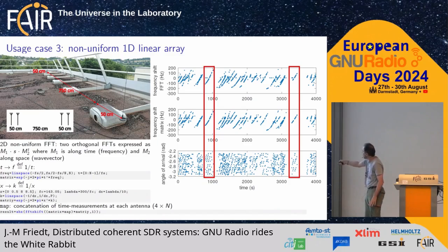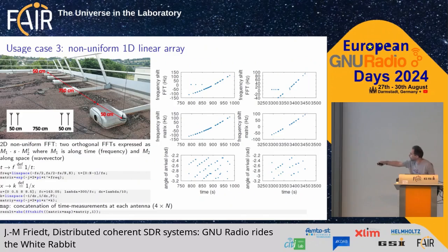So here you have one of the direction of arrival estimates, except that this is over an envelope, and on this envelope you have to do some feature tracking to only follow one track and not the other one. So that's exactly why we have these parallel lines, because one of them is the path of a plane, but we have uncertainty because of the 2 far away antennas.